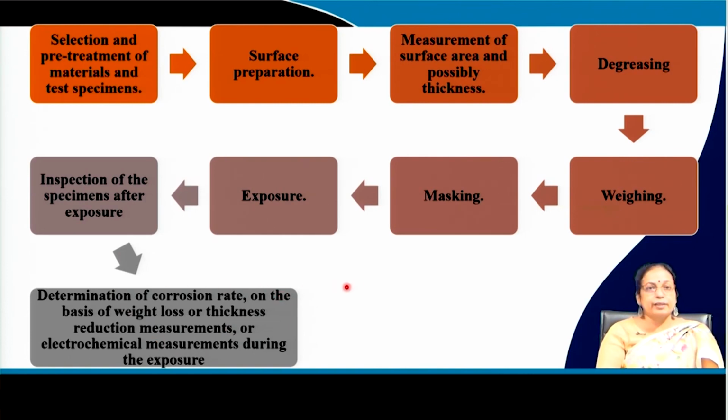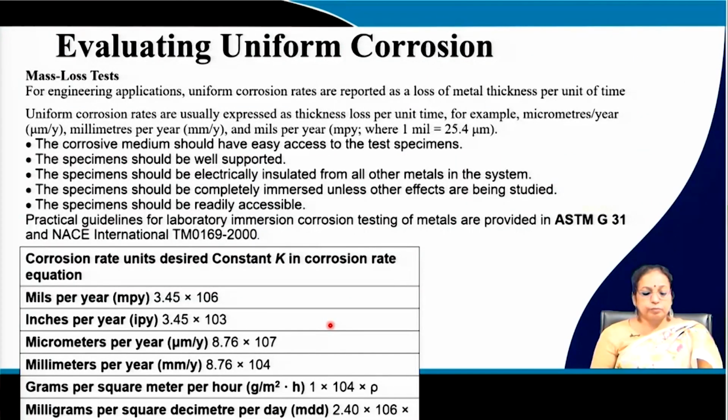You can either apply the electrochemical technique by potentiodynamic polarization, applying potential with the help of a potentiostat, or otherwise you can do simple field testing or coupon testing, where you expose the specimen and subsequently do chemical testing. But the mandatory requirement is that you have to clean the surface properly and follow all the steps essential for corrosion testing prior to testing.